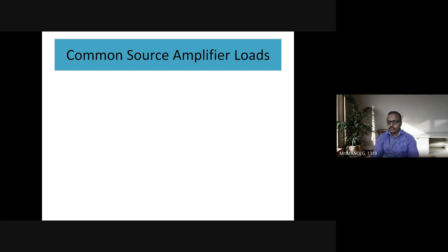In that, we have seen four major types: common source, common drain, common gate, and the cascoded amplifier. And then we saw what a common source amplifier is, and how common source amplifiers are categorized with respect to body effect, that is source generated circuits and source degenerated circuits. I have uploaded the notes in the class for your reference. Please refer to it.